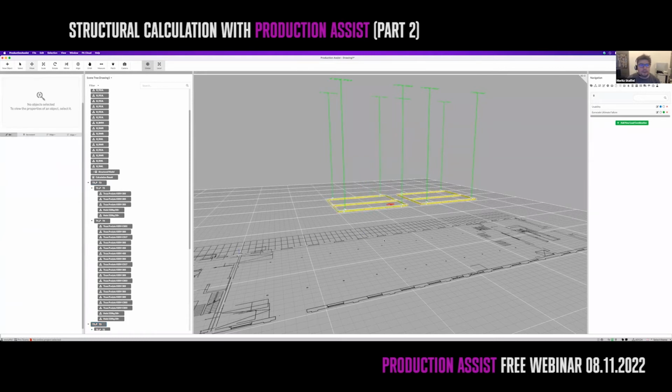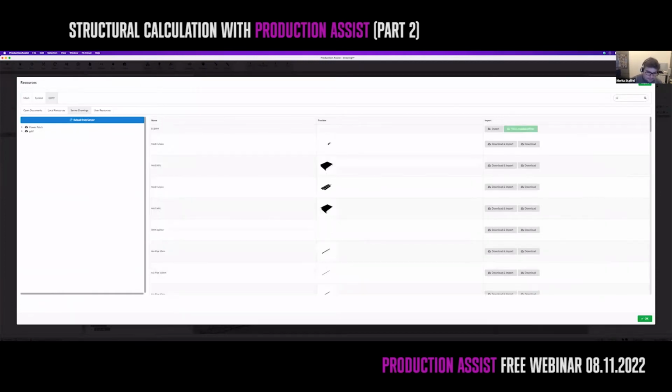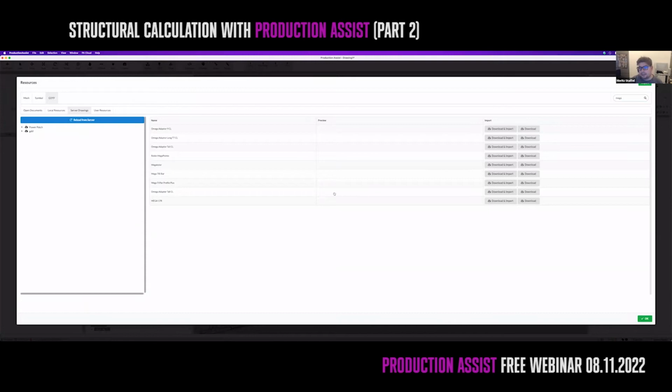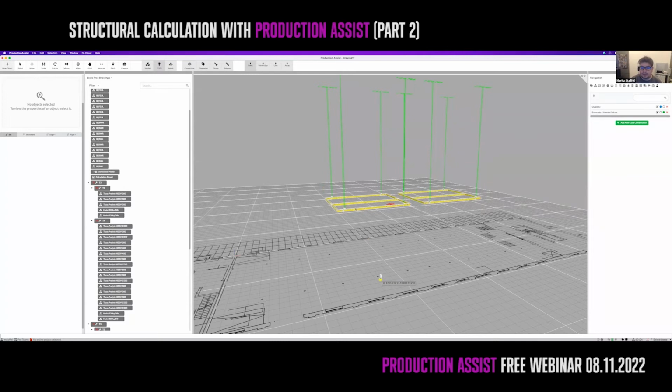Inserting loads like fixtures is really easy. Use the new object tool and select GDTF. Inside the GDTFs, all the fixtures that you have on the GDTF share are available to insert. We will use a Mega Pointy from Robe right now. Selecting this, pressing OK, will bring it so that I can insert it into the drawing.